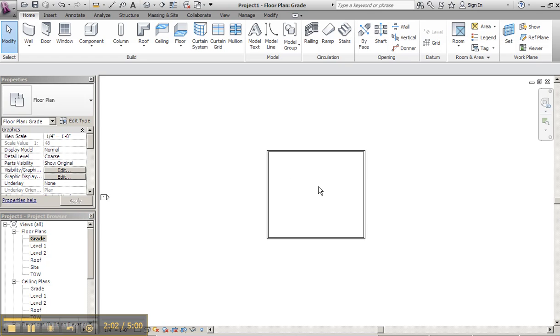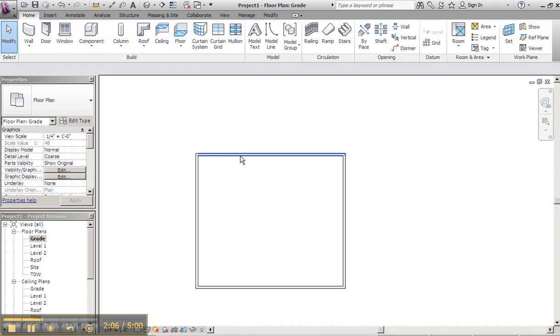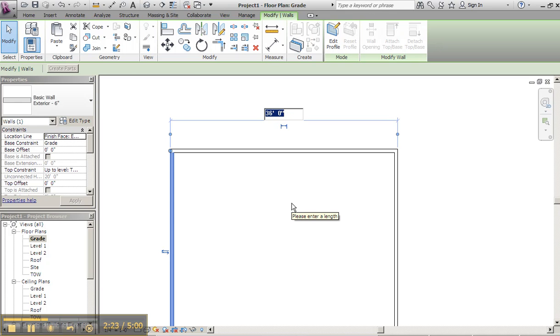Now we're going to go ahead and come in here and we're going to set our 28 feet dimensions. We could drive it with dimensions or we could just use our witness lines. So I'm going to click here. I'm going to toggle this to the outside. Whoops, this to the outside. And that one to the outside. Remember, go center, inside, outside. I'm just going to tell it 28 feet. Now, because this wall is selected, this is the wall that's going to move when I change this dimension. 28 feet. So the wall on the left will move.